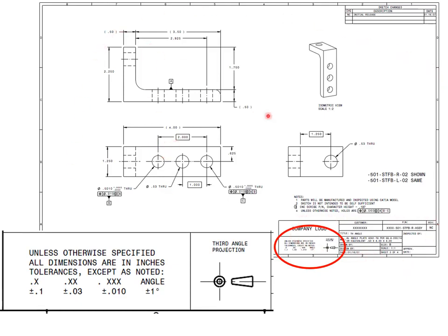Front view, top view, side view. Again, you try and group your dimensions together. You try and keep the dimensions between the views, and you try and avoid having dimensions by themselves on the outside. Here we have an isometric view. And here we have the revision block.